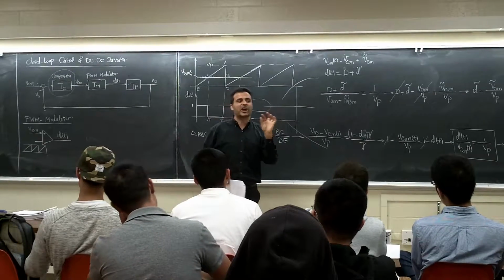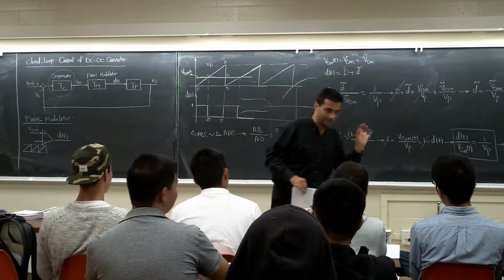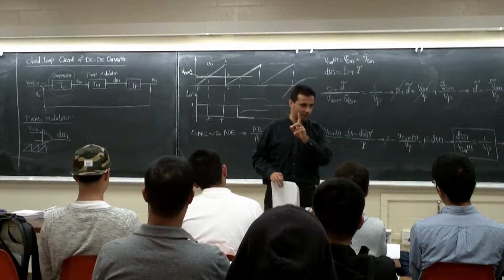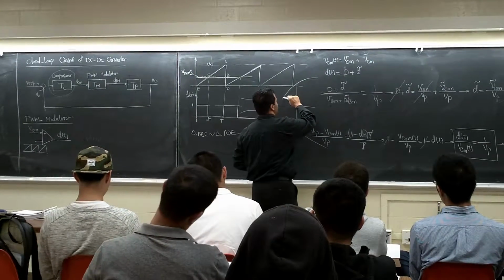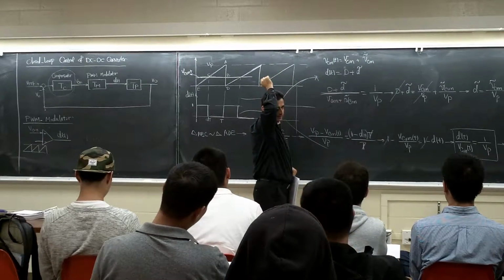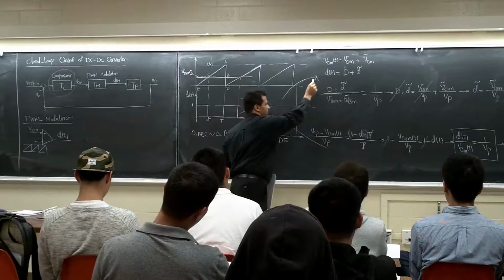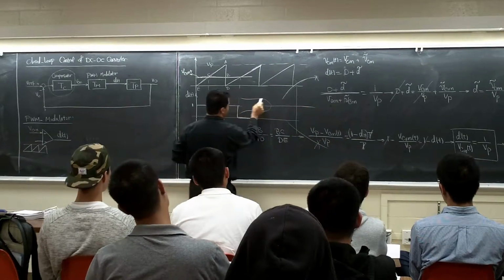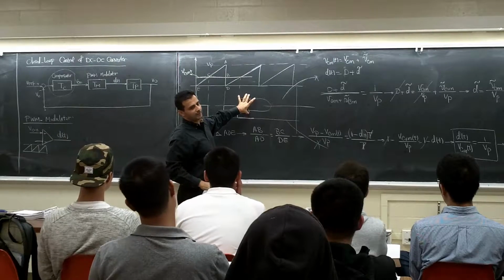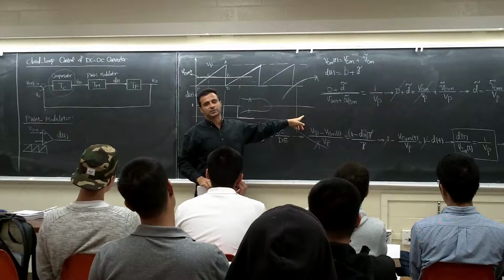Usually there is one K parameter in the system. K parameter is the one you are going to select to design your system. For example, if you go to very high K, you are going to have two poles. For example, here, let's say K is 10. You're going to have it like this. And for example, this one is going to end up here. These two poles, they are good, because they are on the left side of the j omega axis.